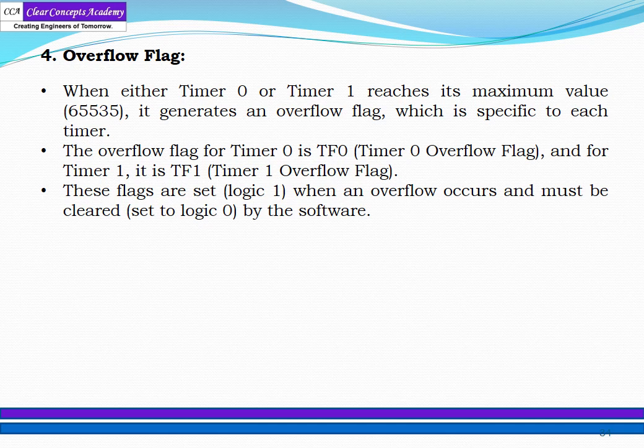To restart the timer, this flag has to be cleared to start the timer again. Otherwise, the timer will not run, because it will treat that as the interrupt still existing.